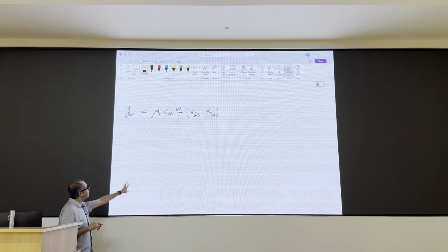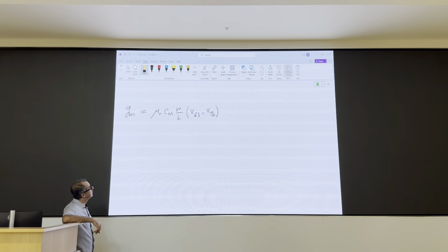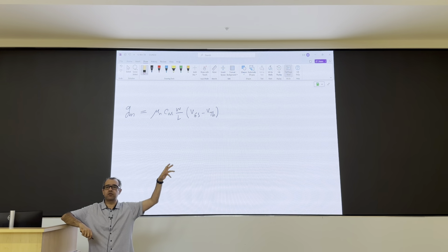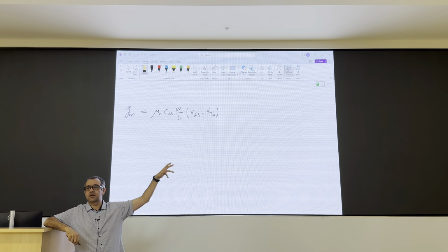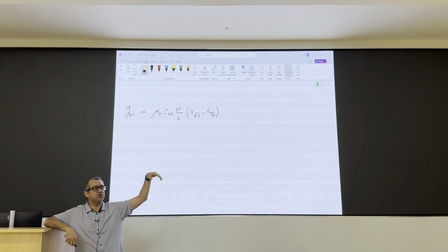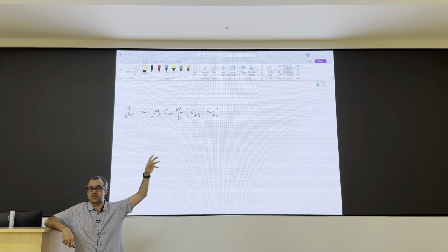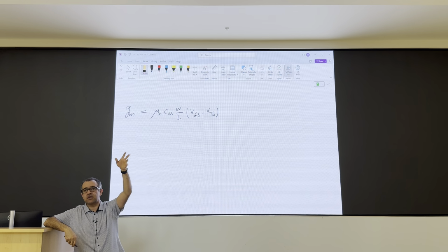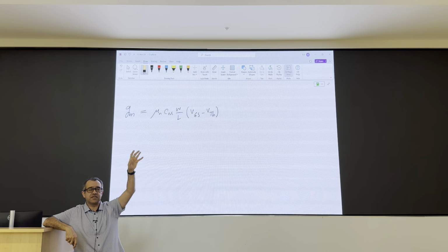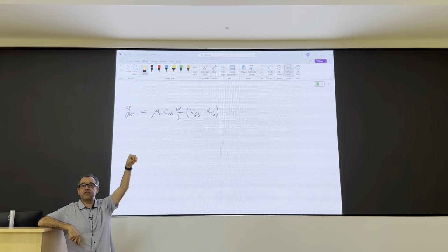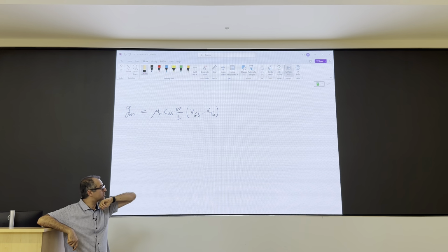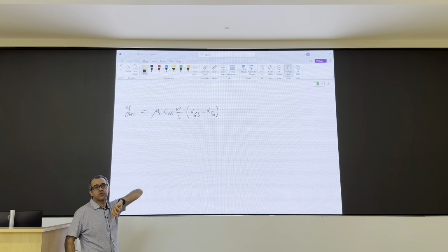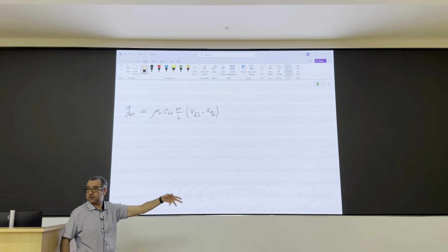So let's have a look at this GM formula here. Right away, for BJTs, how did you find GM? What was it a function of? Just IC. Because VT, you normally do not control. You do not put this device in a fridge or something to change VT. So VT is usually whatever the operating temperature of your device is. You do not play with that. The only way to control GM was by controlling IC. So if you wanted a higher GM, you had to consume more power at DC because that IC was DC